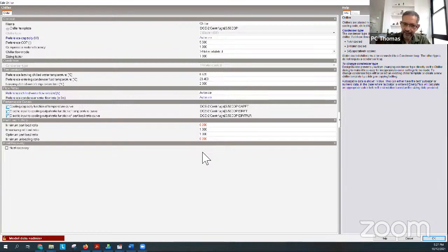So really, the chiller can't run very stably and very efficiently when you are asking it to provide less than 20% of its capacity. Some of them do, but they have things like hot gas bypass, which actually make it less efficient. So why would you want to run a chiller at its most inefficient point when you've got 2 chillers in your plant room?